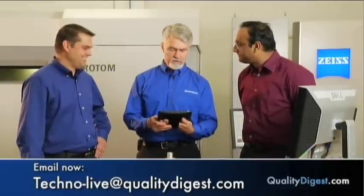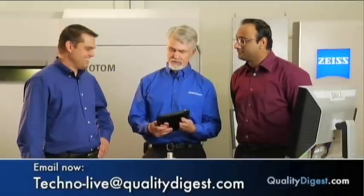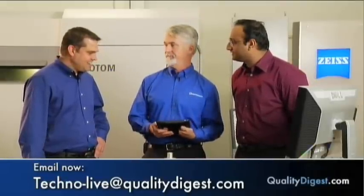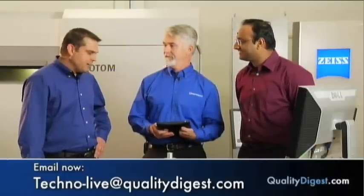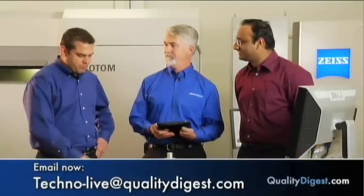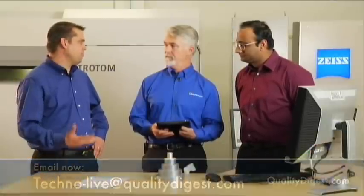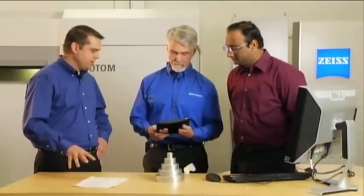How do you retrofit Metrology CMMs with a UC controller, if it has an old ISA card? The problem with a lot of the later Metrology machines is they used a proprietary ISA card for that communication. So Calypso does have an interface with those Metrology machines.